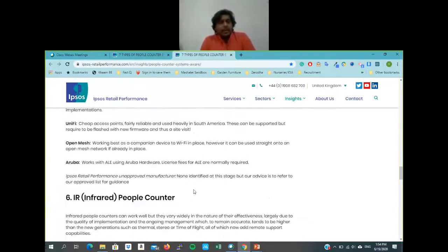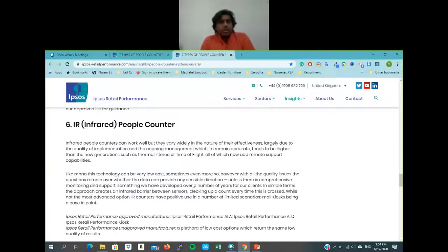by day. And the sixth one is infrared. Now, this is something which I am sure everybody has seen or experienced. The most basic module of this technology is the automatic doors that you see in shopping malls and all. There is an infrared sensor, motion sensor. It has a beam of infrared, and based on the reflection, it indicates the relay to open the gate for you. The same way, the same fundamental, we can count the number of people.